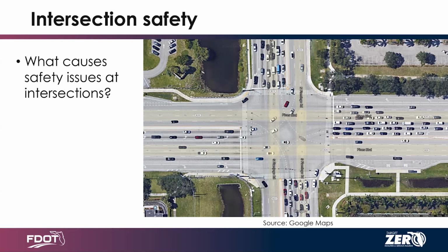One of the key things at intersections that we're going to be talking about is conflict points. Thinking through turning maneuvers, how many lanes are needed to cross, you have a conflict point at potentially each lane. Great things were mentioned, like speeding and poor sight distance. Also, thinking through conflicts between road user types. The crosswalk length was mentioned. Also the visibility of pedestrians potentially being obstructed by different vehicles as they're crossing halfway.